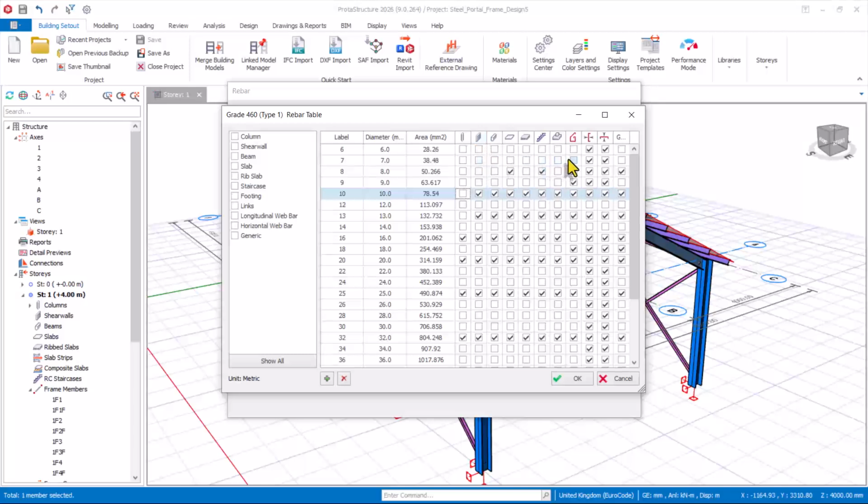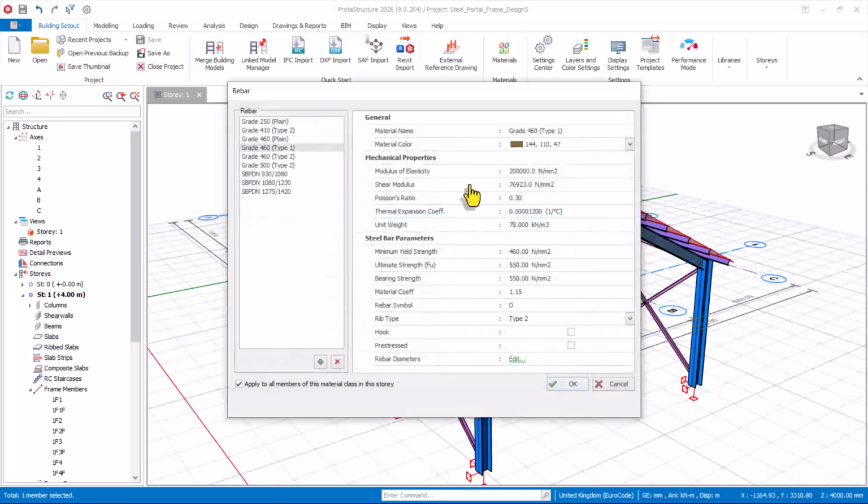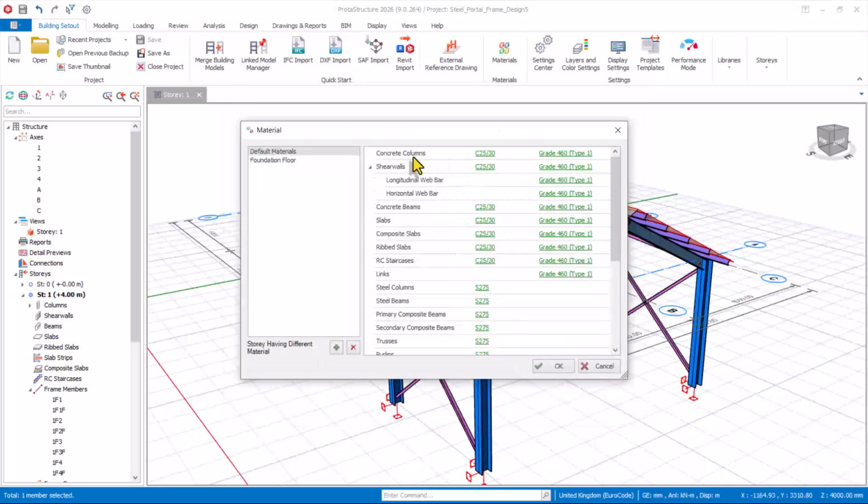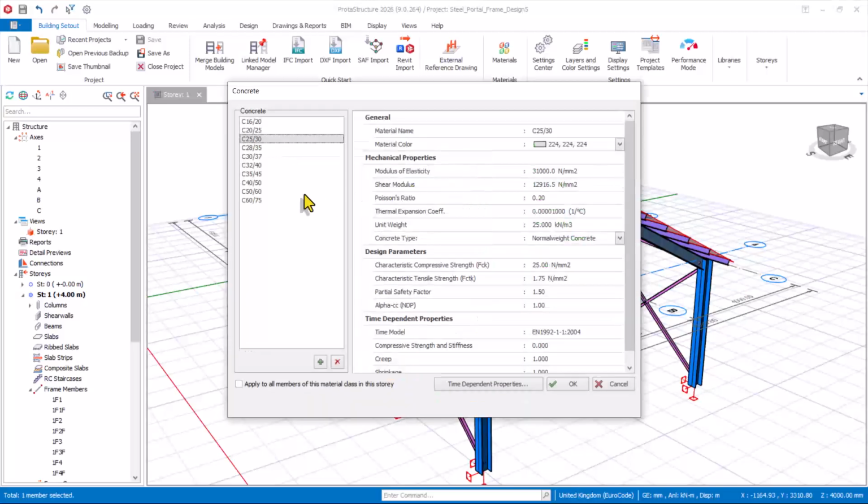If you have any beams from here, we can also go by 16 minimum. If you have any slab, because we'll be designing some basement slab, we make progress. This is good. We click on the OK options and we click on OK. For the compressive strength of the concrete, we use 25/30 from here, applied to all.